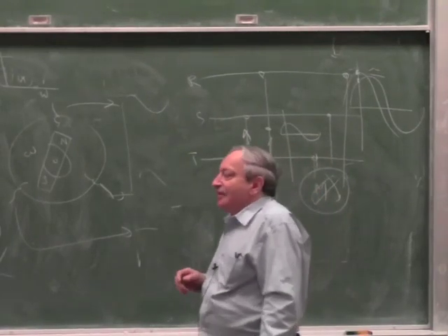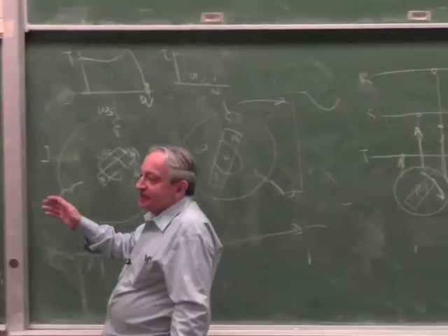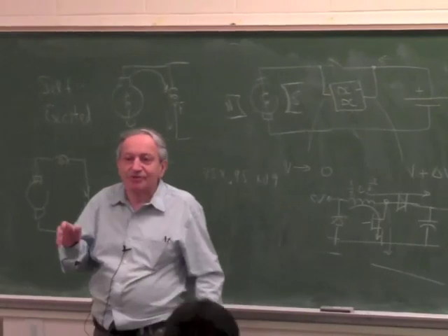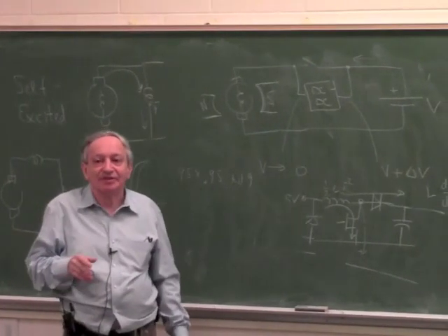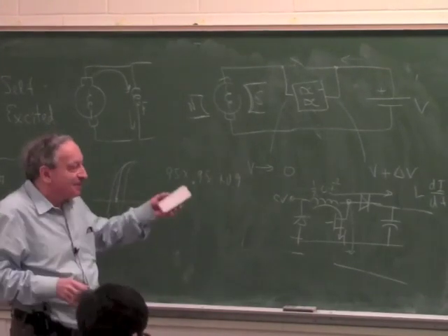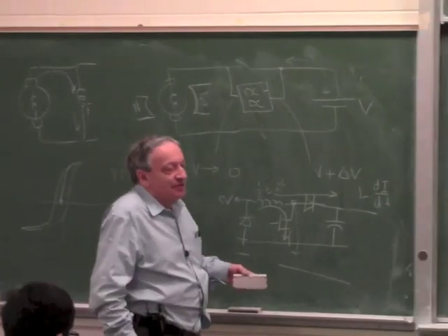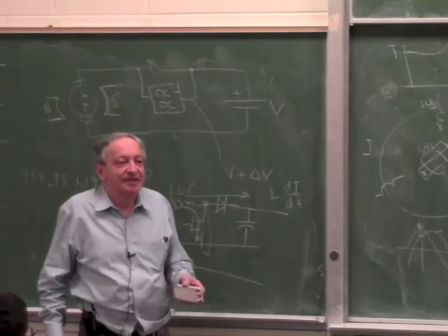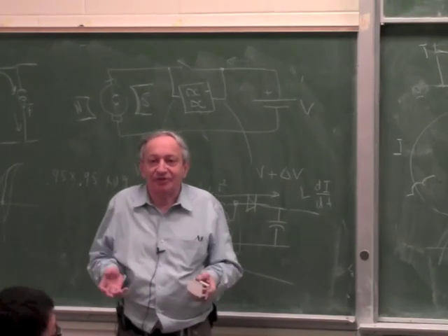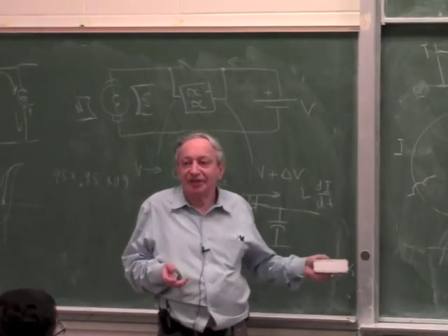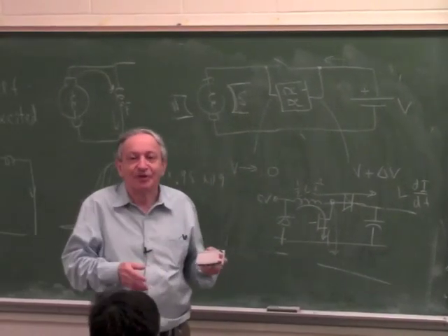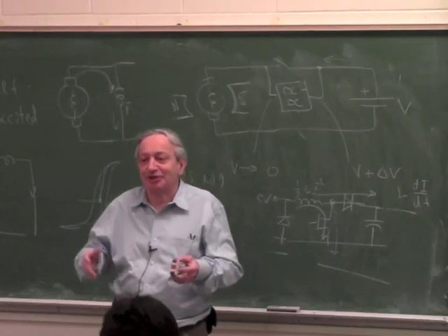Okay, good. Now, all this theory which we always talked about, electromechanical actuators, sensors, motors, also applies to hydraulic and pneumatic systems, because the basic concepts are the same. If you have, let's say, a hydraulic servo and a pressure accumulator, the accumulator behaves like an inductor. It stores energy and has all the same problems. If you want to shut off the flow right away, it doesn't let you. The pressure goes up suddenly.